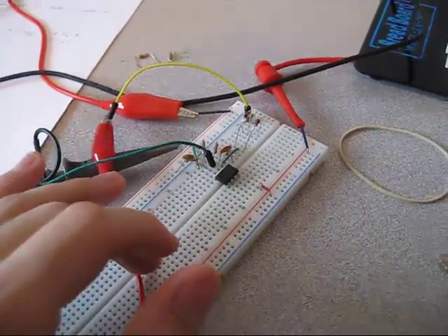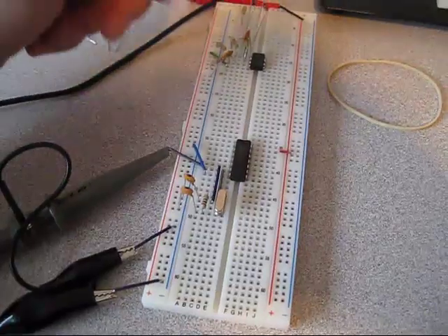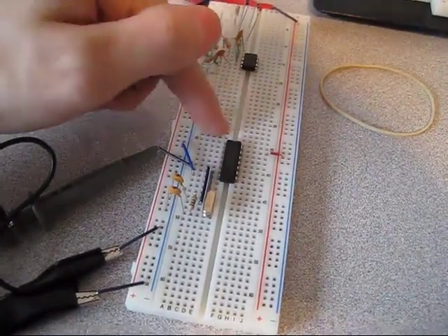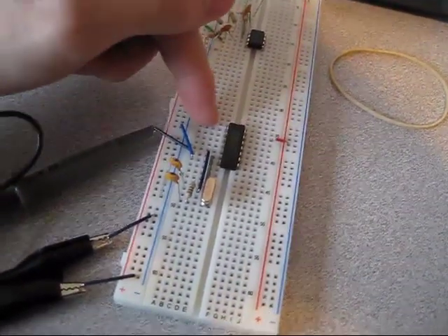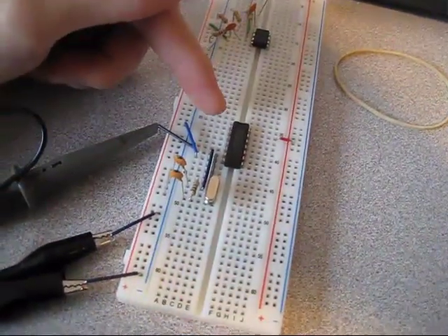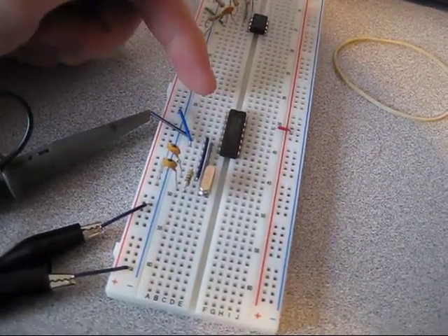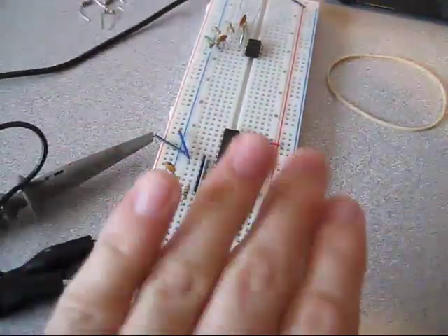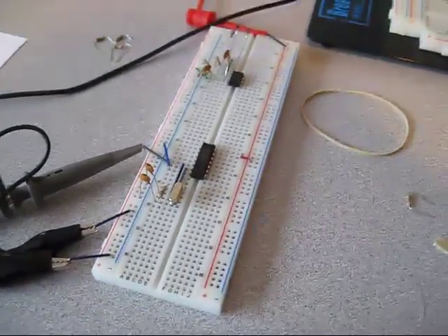Anyways, let's take a look at the other oscillator, the Pierce oscillator. So I'll breadboard that up and we'll see what it looks like. Alright, so I've gone ahead and set up the Pierce oscillator here. And what we're using is just a hex inverter. It's a little bit of an older chip, this one specifically, and thus doesn't run at very high frequencies. I'm already kind of pushing it to its limits here with this particular crystal. If you're interested, it's the 4000 CMOS series. It's the 4069, right? But just this specific one is pushing it a little bit in terms of specs.